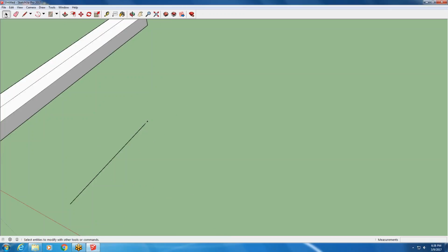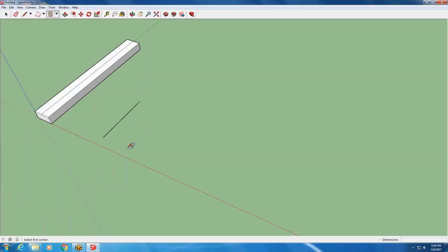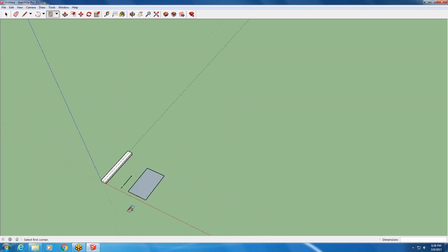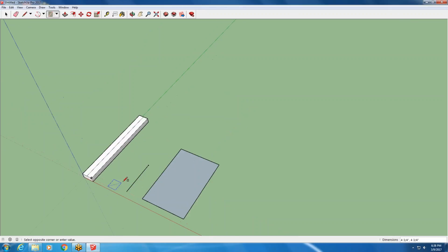So same thing with our rectangle tool. If I type in that I want a rectangle to be 2 foot, comma, 3 foot, enter, we can see it's going to go this way, 2 foot and back 3 foot. So then once you know that, if I wanted this to be a 6-inch by 10 foot in order to give me an overall wall, I could start drawing it, but I want to zoom in.